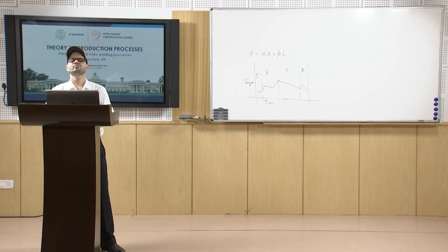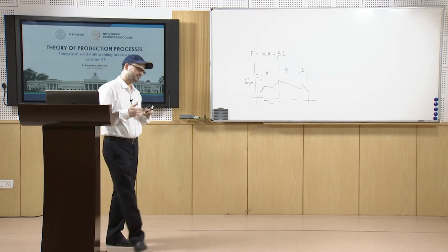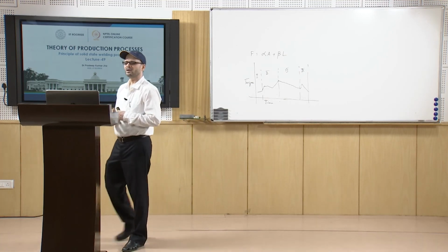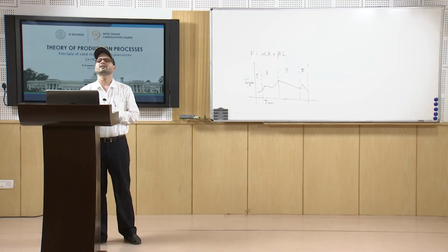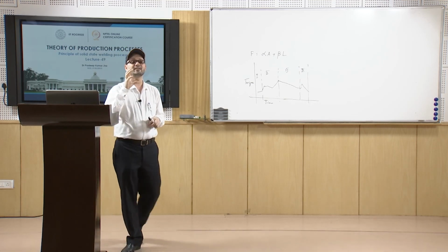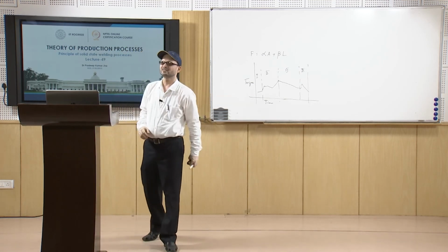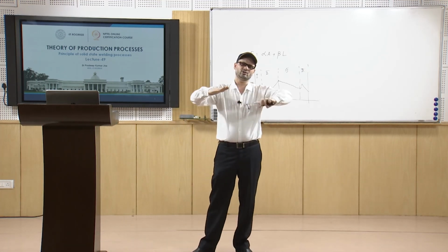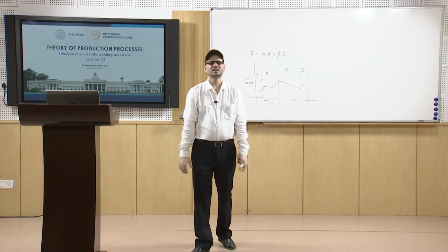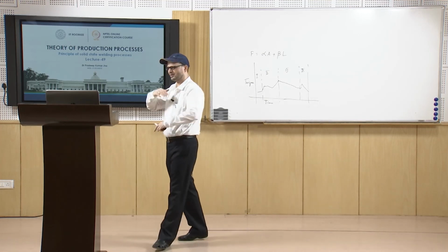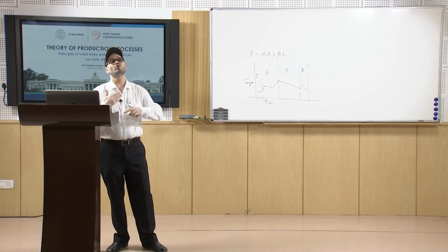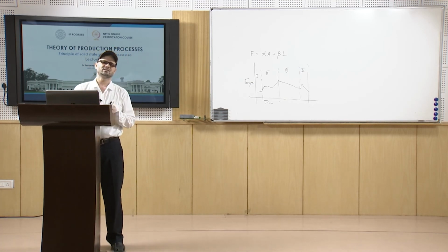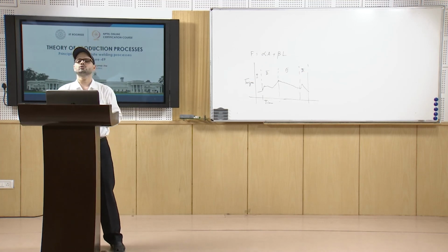Then one of the other types of solid state welding process is explosive welding, where the pieces of metal are joined under impact. So you apply the impact. When the impact velocity is less, you have a smooth or flat surface, and because of that the bonding will not be good. But when it has a high impact velocity, the surface is wavy, and so joining takes place.